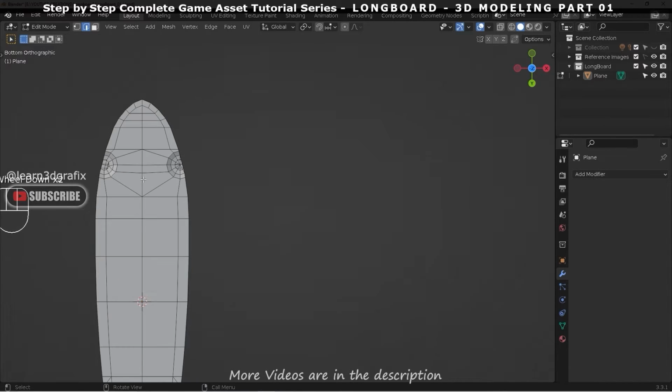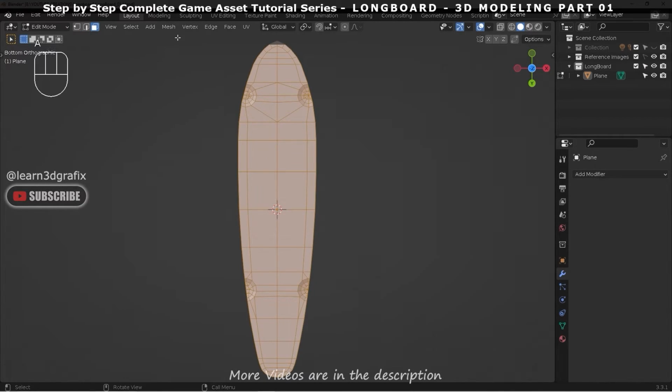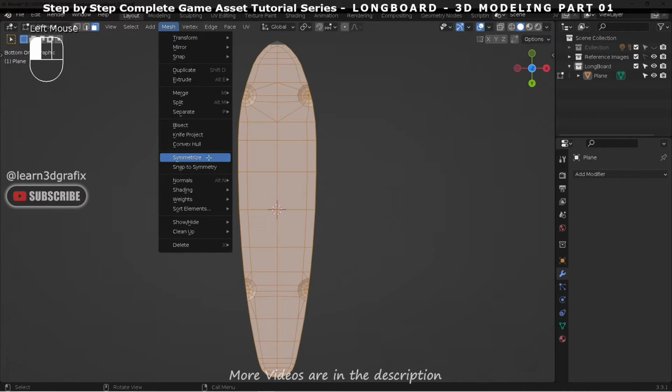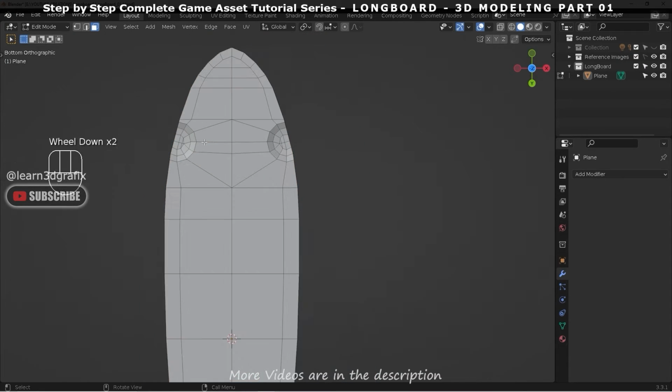It is time to mirror the deck once again to the right side. To do that, press 3 to go to polygon selection and press A to select all the polygons. Now go to mesh and select symmetry. Congrats, you have just mirrored the cuts to the right side of the deck once again.